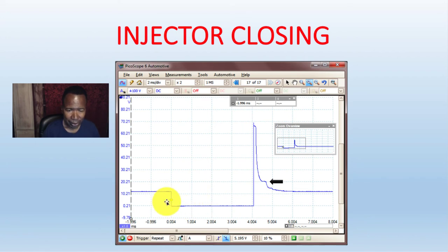So here I'm seeing my system voltage. It's like they revved the throttle here. My injector pulse width got much wider, almost 4 milliseconds here. But now, once that throttle is released, this closing right here is going to come all the way over here, indicating the injector is closing.